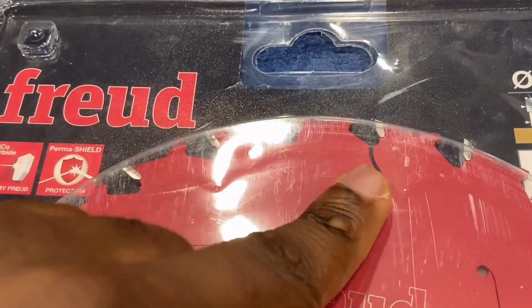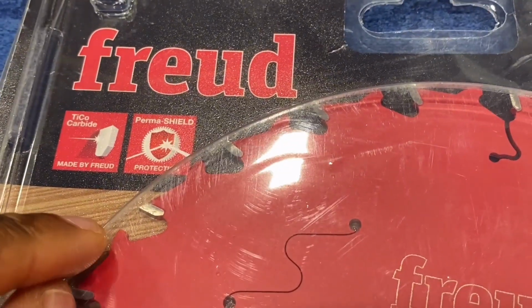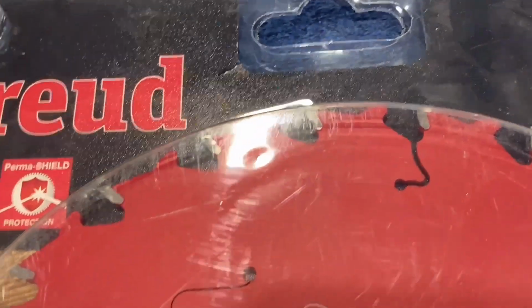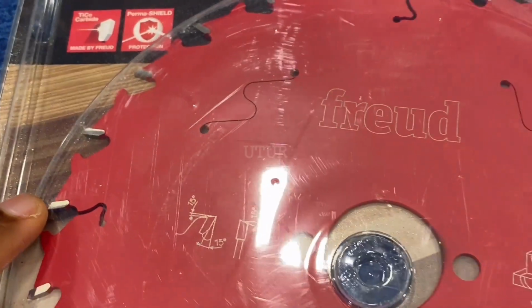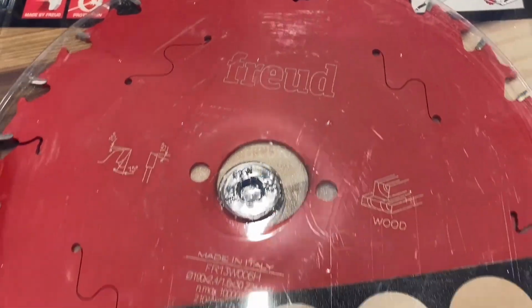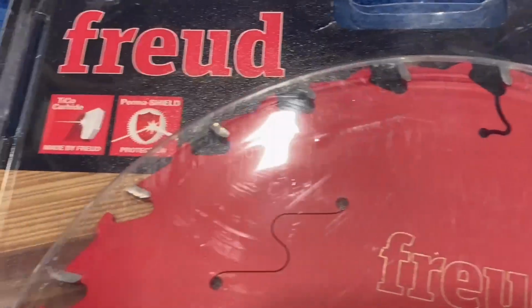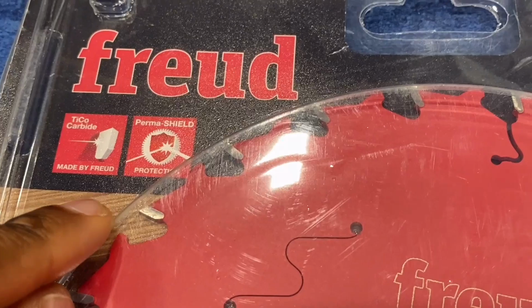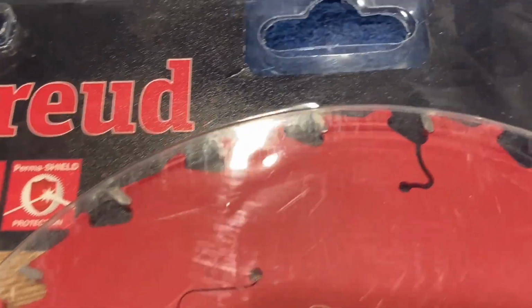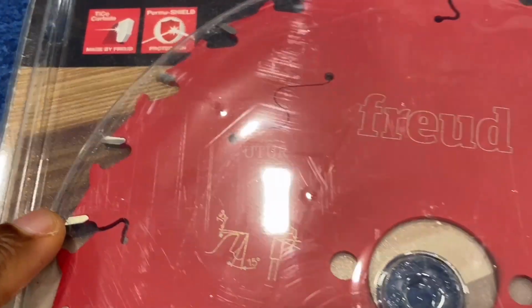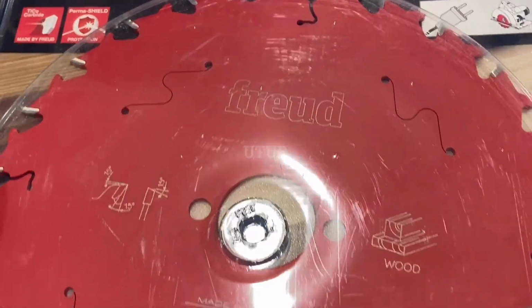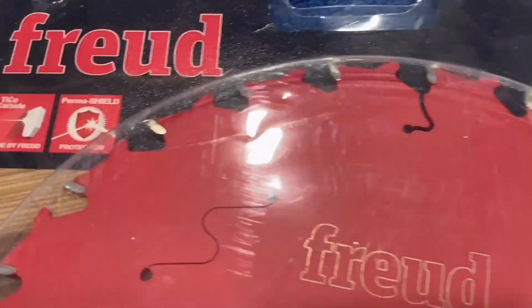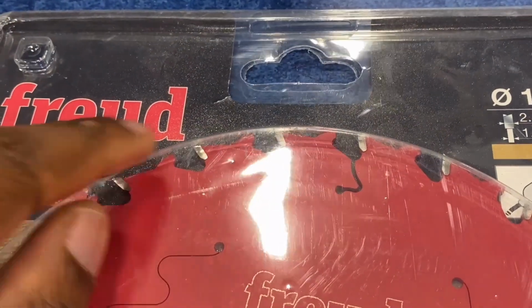You'd get great finishes for your ripping, and you can use it to cut along and across the grain of the wood, if you also want to cross-cut, okay? So it will do a pretty good job of both ripping and cross-cutting. But you might be better off using this as a ripping blade, as it's got larger gullets, and you can extend the application to cross-cutting, as it's got a positive rake or hook angle at 15 degrees.